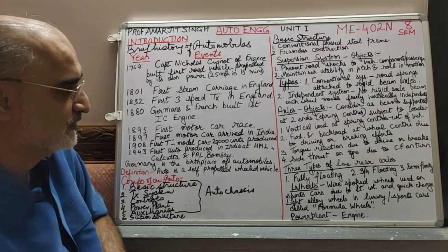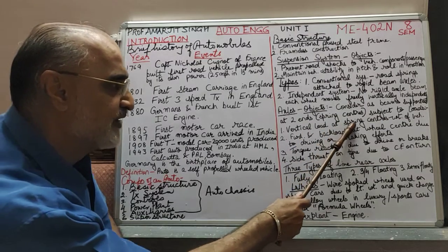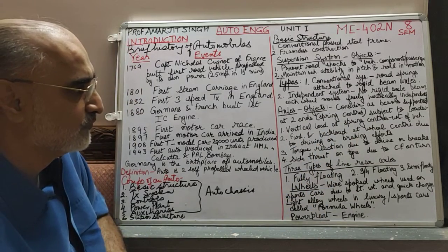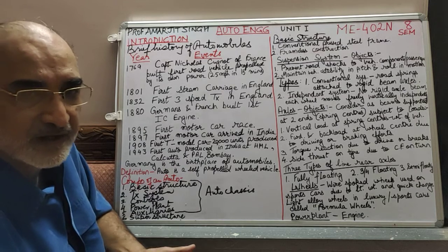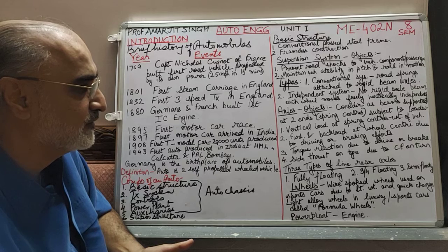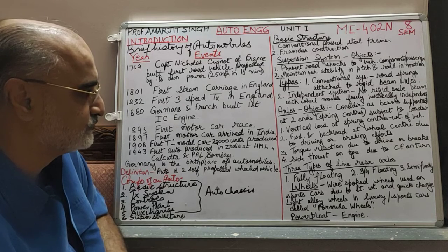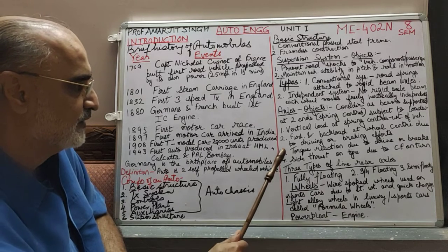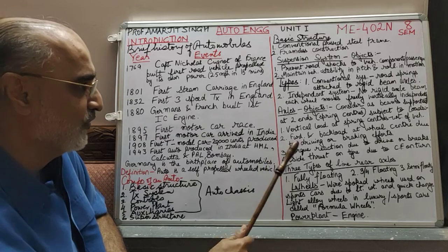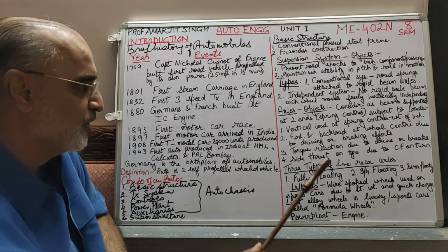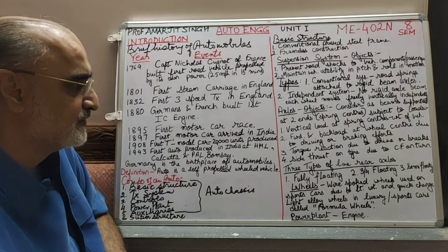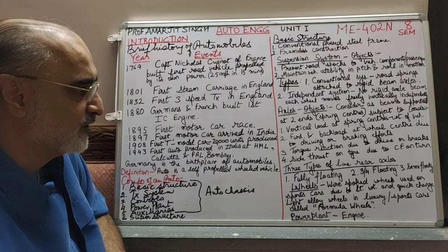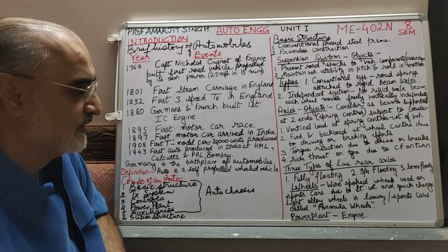First, the vertical load at spring center, which is nothing but the weight of the vehicle and its occupants. The second load, forward and backward at wheel centers due to driving or braking efforts.